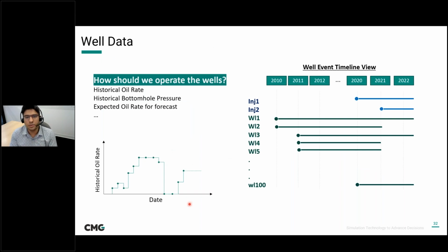And as I mentioned, we have the container, we have the fluid. Now, what is our tool to get the oil out of the reservoir? It is wells. We do this through drilling and completing production wells, or if you're looking into any enhanced recovery, we can do this through injection wells, whether it's water flooding or gas injection. So we need different tools to be able to quickly define wells and operate the wells under different conditions. For instance, imagine that you're in the history matching period.